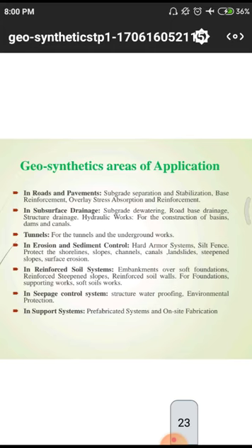In those cases we are using these reinforced soil systems. First of all, we have to construct an embankment over the soft foundations, and after that we need to give this reinforcement in the embankment by using these facing elements and other substructures. These steepened slopes and reinforced soil walls we have to utilize for the purpose of foundation supporting works and soft soil works.